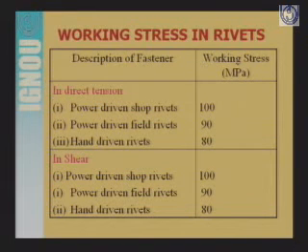In case of shear also, similar values are given by the code for power driven shop rivets, field rivets, and also the hand driven rivets. So I would like to suggest you to go through the IS 800 code and find these different working stresses, in different types of stresses, that are given in the code.